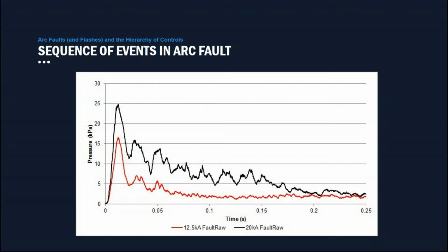But we can see the red line and then the black line, very steep initial rise, and then once the vent has opened, in the red case it drops fairly quickly back to a low pressure of around 2 kPa. In the 20 kA case we see a little bit of resonance in there. We haven't done detailed mathematics to understand that, but we understand that would just be some resonance in the enclosure, so that is, if you like, the air rushing in and out through the port. But nonetheless, we see from a very steep initial rise, the pressure drops quickly.